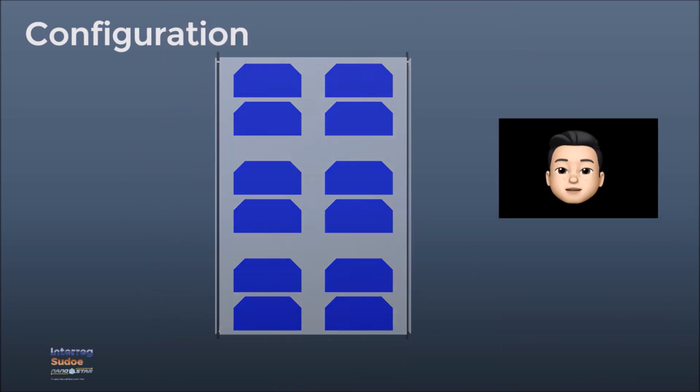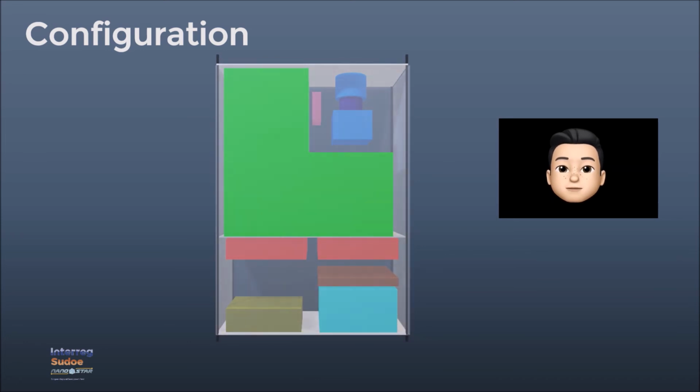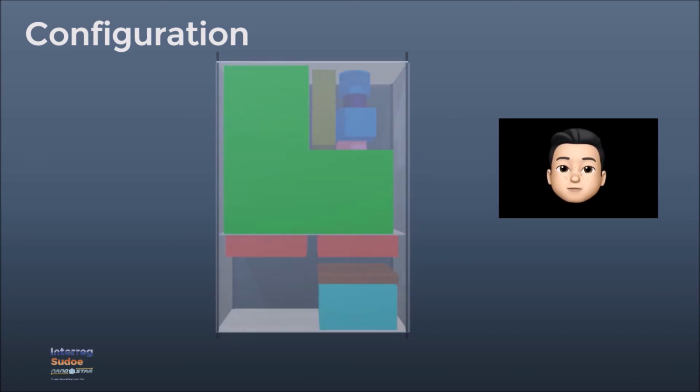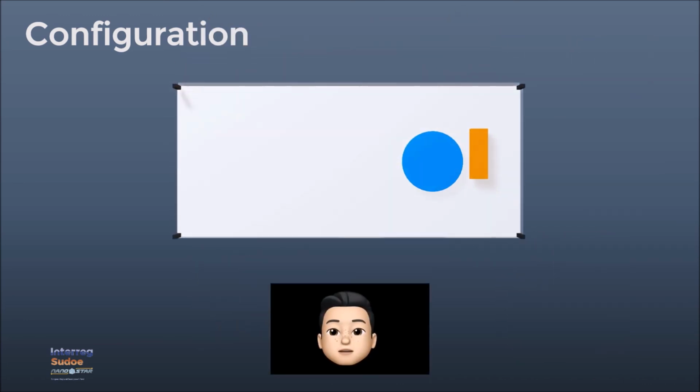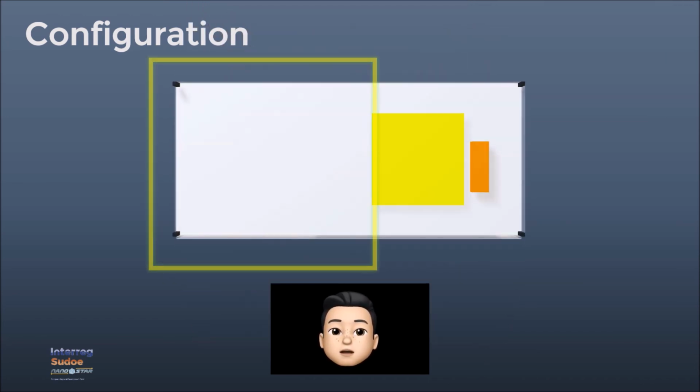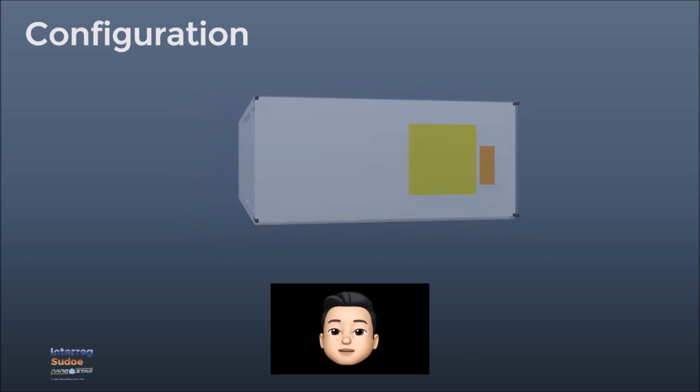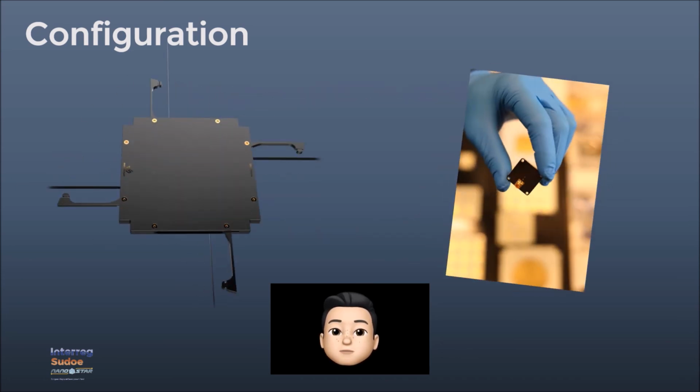This mass margin implies that if some of the elements are rearranged, such as the radio and the IMU for example, there is an empty slot that could be filled with a secondary payload, redundancy, or even the primary payload could be enlarged if the NANOSTAR payload department decides so. There are also available two 1-unit surfaces, one at the top, one at the bottom, that can be used to carry secondary payloads such as antennas or small patches, so any company that wants to test a new component is welcome to join the project.